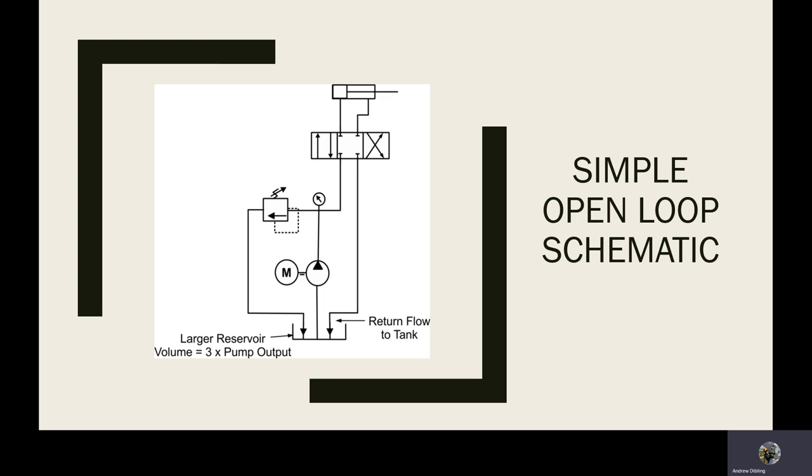This is a pressure relief valve. On top here, you see this squiggly line, which means that it has a spring set on it, and that this arrow indicates that it is user operable. So the user can actually determine the set pressure of the system. And again, I mentioned that this is a safety device. You don't want it going off all the time if it doesn't need to.